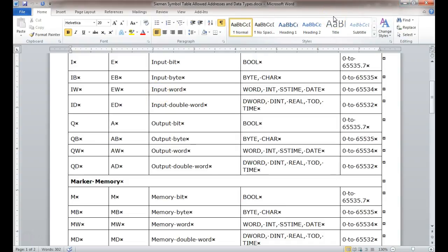And of course what Allen-Bradley did, and like I said, I need to learn the 5000, but what RSLogix 500 did, it dedicates memory to certain types of data, like F8 and N7 and stuff like that. What Siemens, or what this application does, is it allows you to control your memory. But now you got to keep up with, I've already used this, or I already used that. Because if you use QW, it's not going to say, well, you're already using that word for something else. It's not going to tell you that, right?